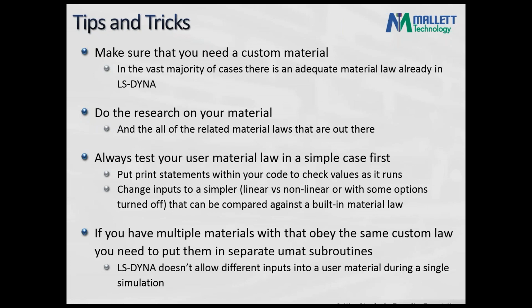And the last thing here is, it's not the best feature of LS-Dyna, but if you have multiple materials and you want to use the same material law, you have to put them in separate user material subroutines. There's 10 available, so you can't have different parts in your simulation use different inputs with the same material law. You have to copy it over, which is a little frustrating, but it's definitely something to keep in mind. And you almost never see a case where you have 10 different custom materials in your simulation anyway, so it's not a limitation.